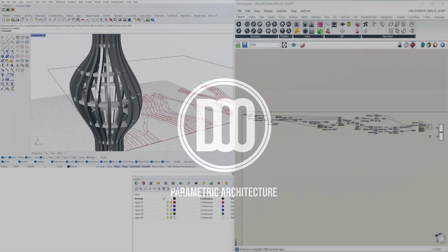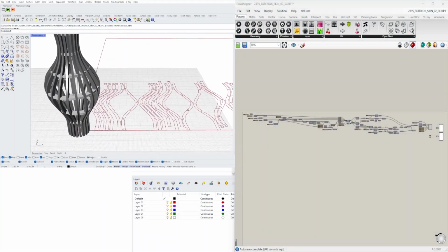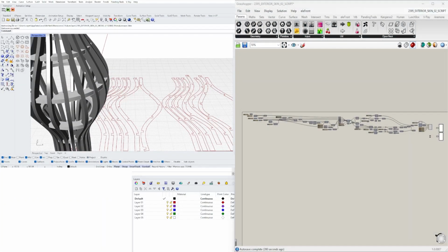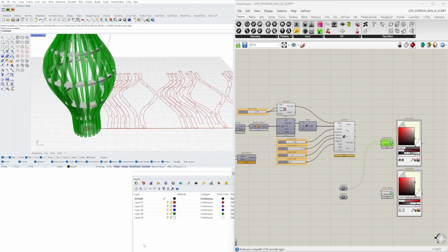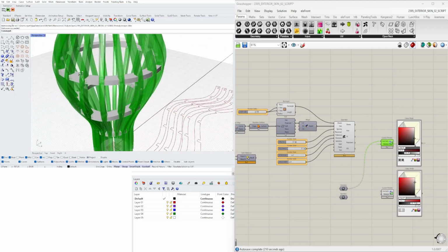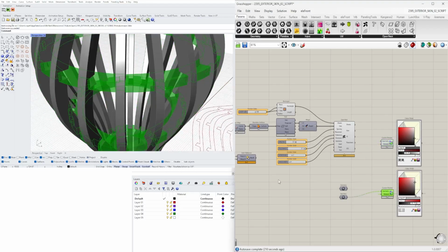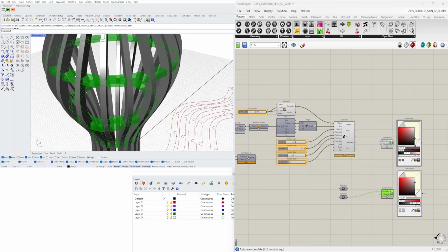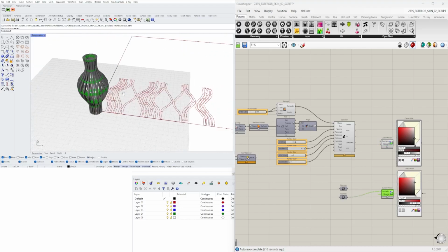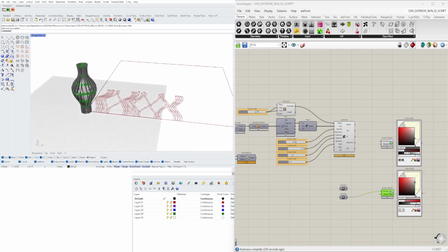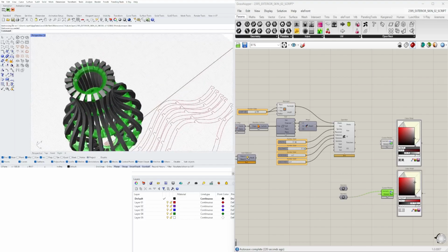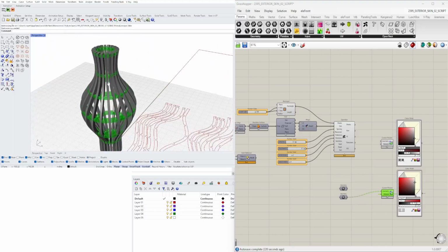On this design, there are notches not only on the verticals but also on the horizontals here. So what you'll see is that if we look at these, they are notched, and if you look at these, they are notched as well. That will make it so when you CNC or laser cut it, they will intersect here, and it will be an easy way to fabricate this.